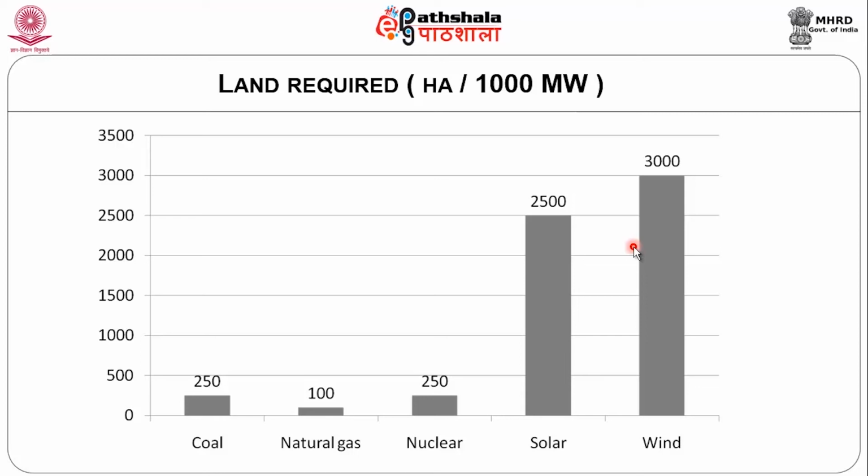So the maximum we can go up to is 59.3%, but because of practical reasons, the best turbine could perform with 40% capacity factor, and generally the wind farm capacity factor would be around 0.25 to 0.3, that is 25% to 30%, but the best wind farm performs at about 40%.